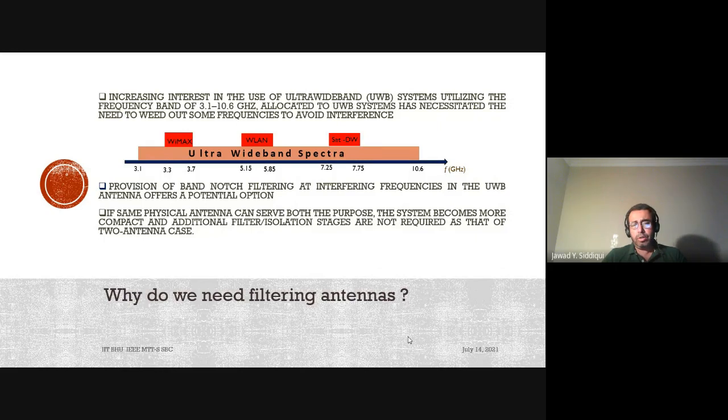We have seen a lot of work in antennas having defected ground structures, and you can do a lot of engineering in the physical geometries, which will tune the frequency, filter some of the frequencies, as well as increase the bandwidth. It's all basically a part of the game of how you design the geometry of the antennas and the excitation of the modes that we want to radiate.